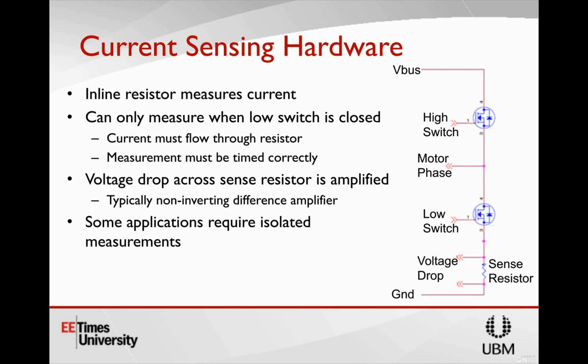Most of the microcontrollers that are directly targeting motor control applications have the logic required to do this. You can set it up so that it'll trigger an ADC automatically based on when the hardware pulse width modulation module says the low side switch will be closed. So that's something you don't necessarily need to worry about with most microcontrollers.